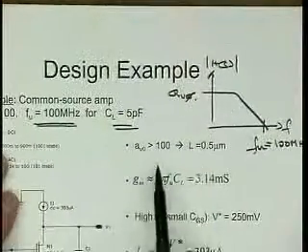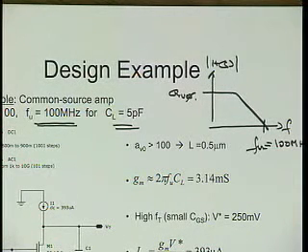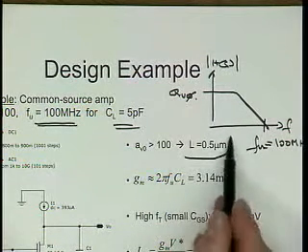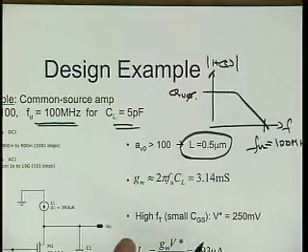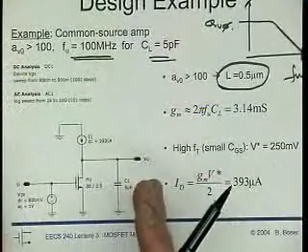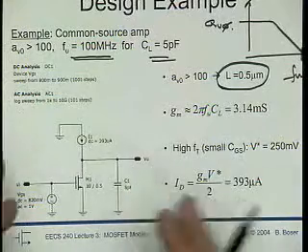Okay, so because I said I wanted to have really high gain, and I know already that 0.35 micron isn't going to cut it, and 0.5, well, I had a slide, certainly it went all the way up to 280, so 0.5 micron might make it, right? So let's try a half micron transistor, so that we have a chance of meeting our gain requirement. Of course, later we're going to build more complicated amplifiers that have more than one transistor, and one transistor is not responsible for giving us all the gain.